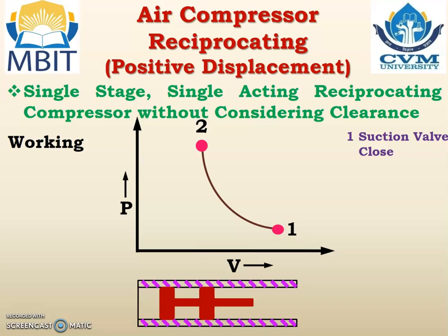Here it can be any process, maybe polytropic, maybe isothermal, maybe adiabatic. So let us consider 1 to 2 is the process. At point number 2, the discharge valve opens. As the discharge valve opens, high pressure air is transferred to the storage tank.